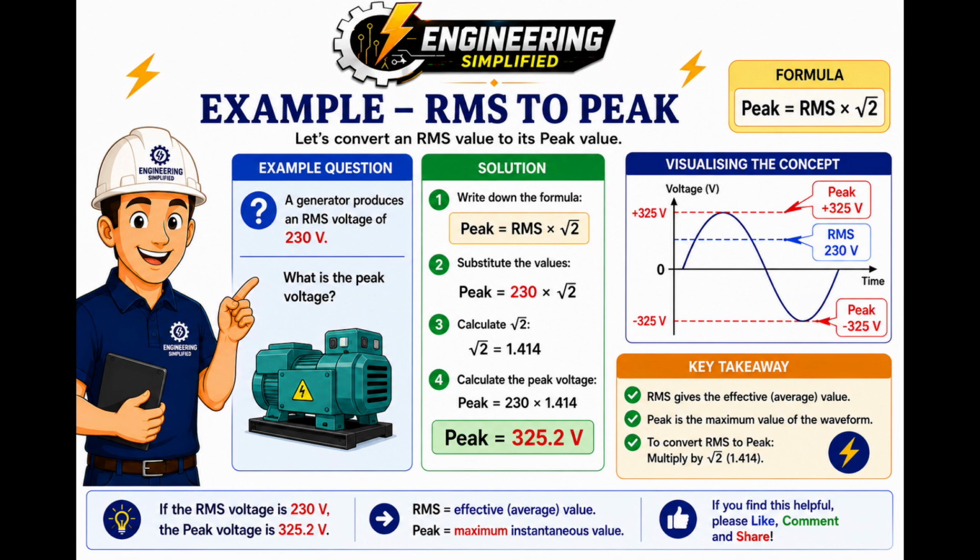The formula is peak equals RMS multiplied by the square root of 2. Substitute 230 volts. Peak equals 230 multiplied by 1.414. That gives approximately 325.2 volts. So a 230-volt RMS sinusoidal supply has a peak voltage of approximately 325 volts.